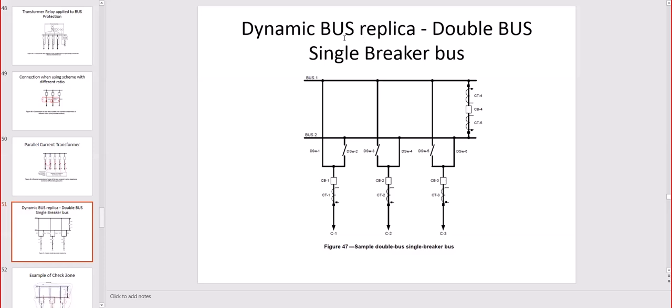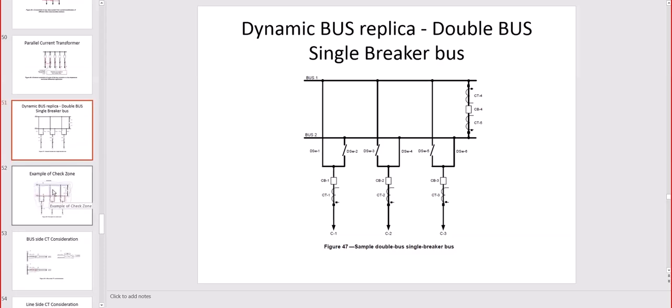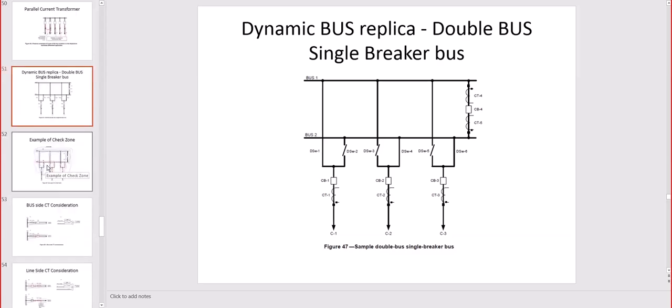Then you have 87 for motors and generators. They have exactly the same idea as a transformer. Don't forget, a transformer is just a particular case of a motor, induction motor that doesn't move the secondary. So all the protections pretty much from this point of view, 87 can be related to a large medium voltage motor or a medium voltage generator, large generator as our main generator, or EPGs and SGs.